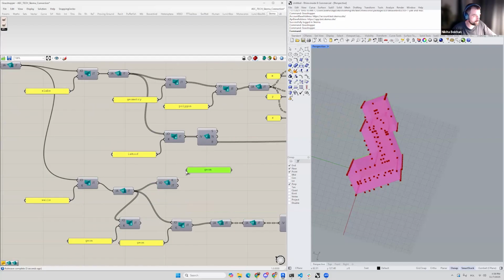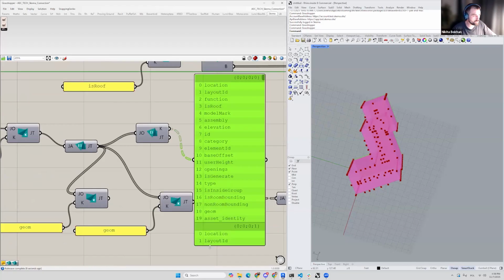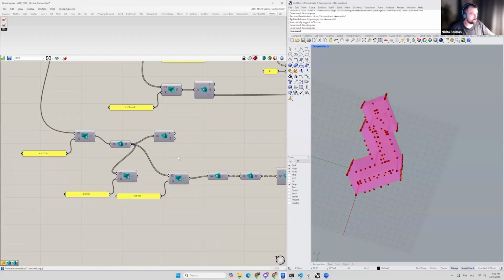Here, and read all my keys. So as you can see, our walls have a property elevation, which gives us the elevation of each wall, because this is how it's easier to reconstruct in Revit. We need to know start Z and elevation in this case.